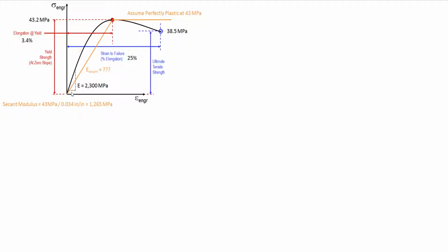Or you take a 3D printed ABS part and bend it a lot, and you let go, it returns to its original shape. A long piece of acrylic, you bend it, look at how bowed it is, and then you let go and it returns to its original shape. That is basically what the elastic region is. It's the important region because we don't want our machines to lose their original shape. You load it, and it unloads itself after you remove the load, and it goes back to its original shape.